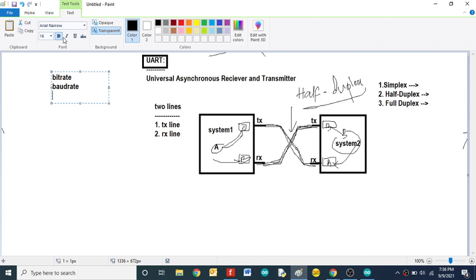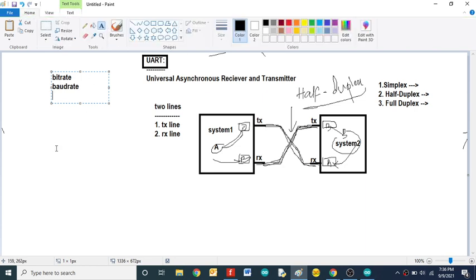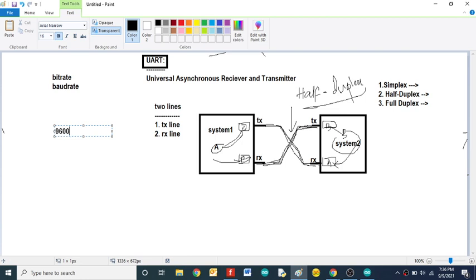Okay, so for most microcontrollers the recommended baud rate is 9600 baud. So at that baud rate the information will be transmitted. You can take 1 divided by 9600, so this is the rate of transmission. Okay, so like that, we have to set the particular baud rate for achieving the particular communication speed.